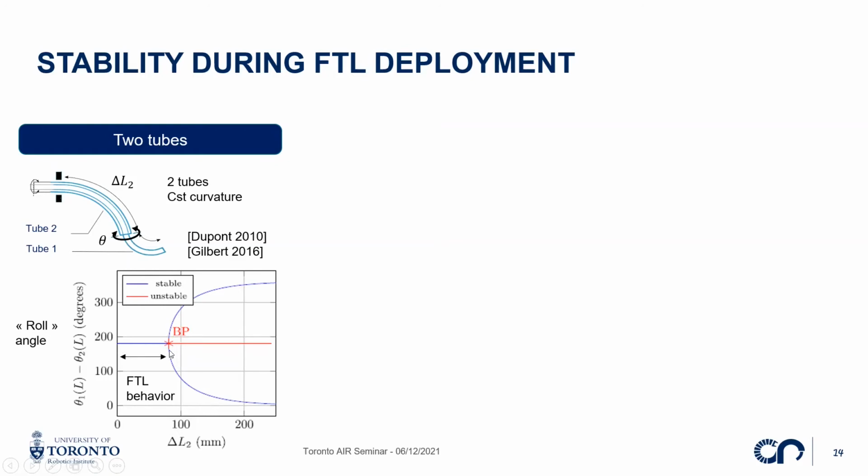At some point, we encounter a bifurcation here, and the robot starts to experience torsion and has different configurations for the same actuation values. And we know, I have to stop saying basically, it's horrible, I apologize for that, we know that the robot follows the leader behavior on this specific portion before the bifurcation.